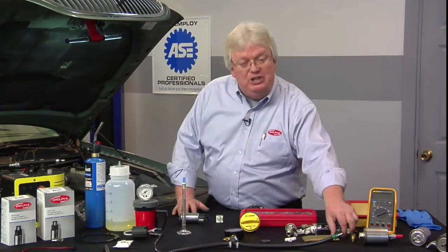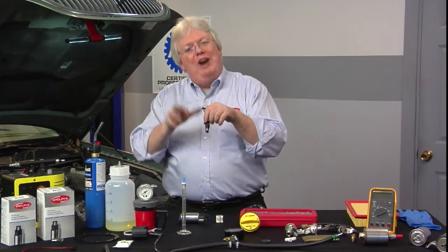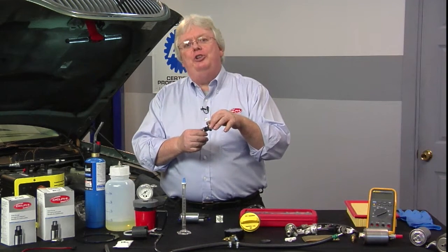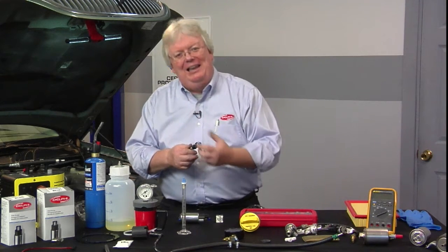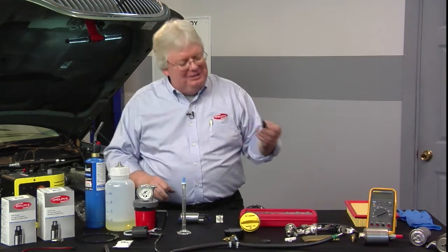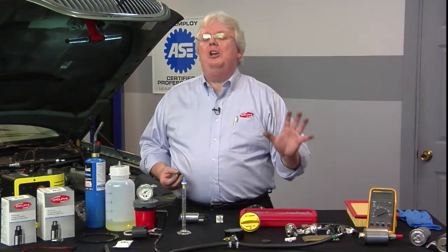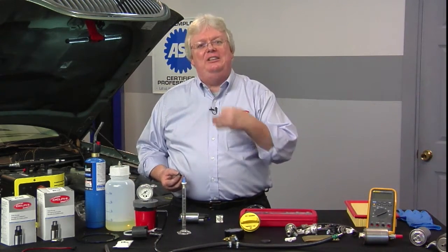We could have drippy injectors, so we want to make sure we look at the pressure and do an injector pressure drop test. Also, there are tricks you can do with your gas analyzer to see if the injector is what's dripping, and on an oscilloscope as well. A skewed O2, a bad O2 sensor could cause rich or lean. It could be sensing falsely.